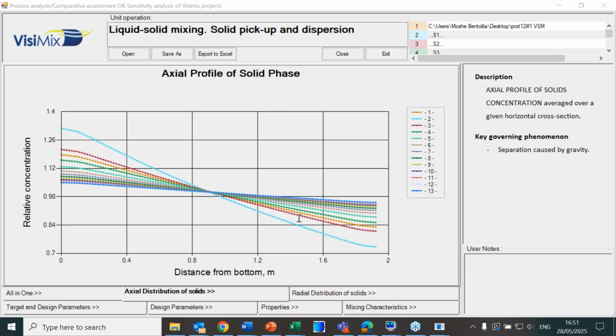that will be possible to run. Okay, because as I showed you, when we go to scale up, we are doing some activities about the same solid-liquid, but after that we have a problem with the mixing time, or another one, because it's a multidimensional phenomenon. So take care of it. Okay, from the design point of view, we need to design in a range of work that will be good for my process, and it is not always high velocity, high shear rate, or homogeneity. I explained in the presentation, in the motivation, how they decided that the solid distribution should be homogeneous, that it was good for the process, and the answer was that the process was not good.